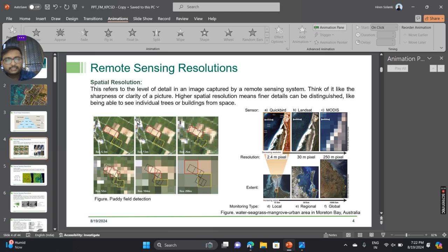If we keep our satellite too high, if the altitude of the satellite is too much, then we will see that the entire Taj Mahal is just one pixel. It will create a very coarse resolution image. And as we go down, the details will become finer and finer, and then we will be able to resolve the Taj Mahal properly. So whether we are able to resolve any given feature or not, any farm or not, any lake or not.